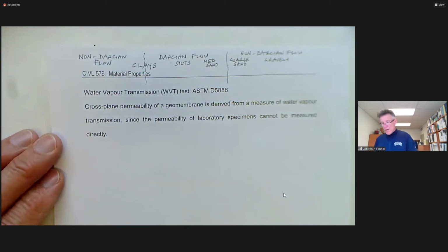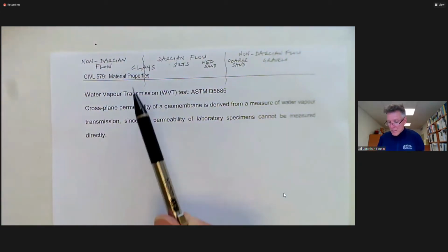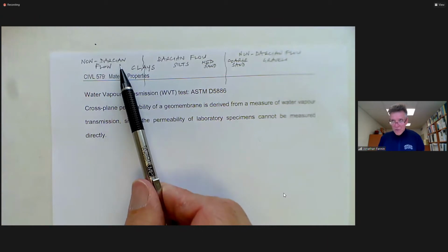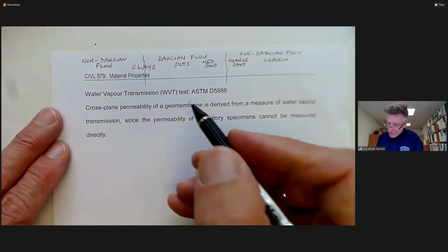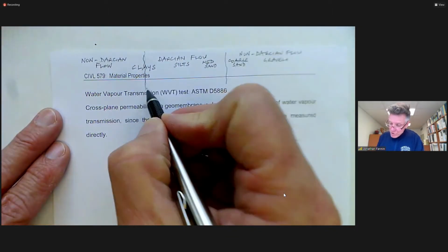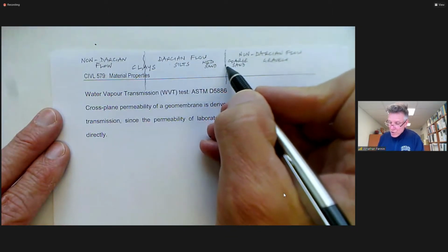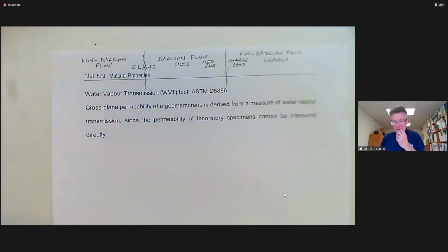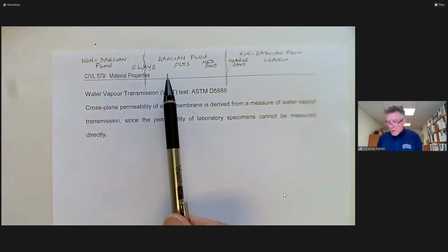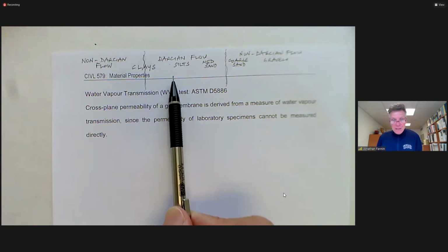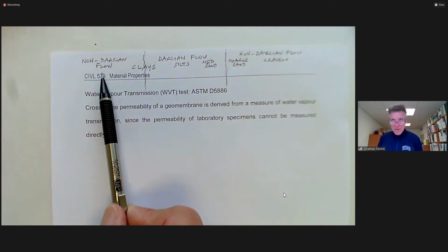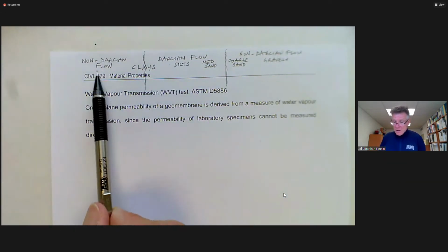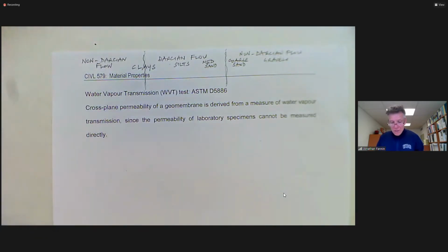If we have very low permeability clays, observations of Darcy's law being applicable also break down. So Darcian flow is occurring in a sweet spot of porous media in which the flow regime is laminar. It breaks down with very coarse porous media, and breaks down with very, very fine non-fissured clays.